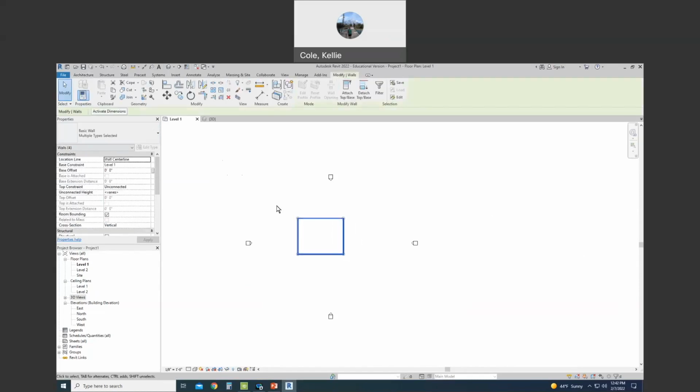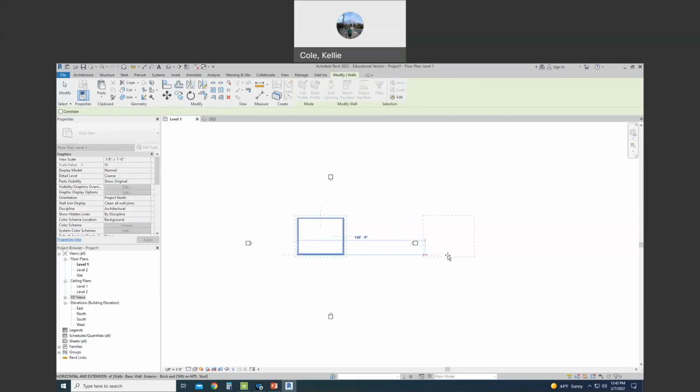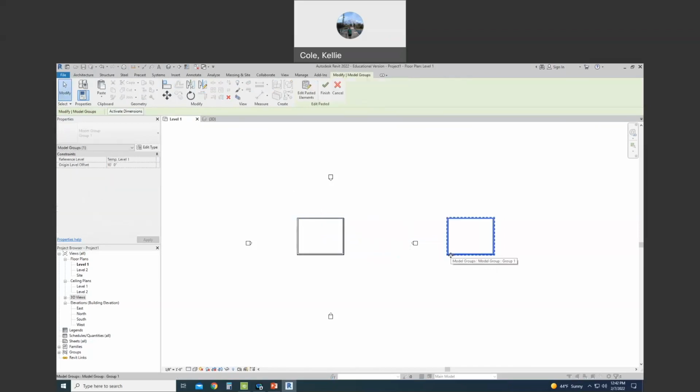Again, I'm just going to click on the upper left-hand side, drag my mouse right, hit Control C, and when I hit Control V, notice that here I have nice dimensions. I have a ghost of what I'm trying to paste. Why don't you paste it, I'll come back, 150 feet off to the right. I'm just going to hit 150 feet, enter, right?